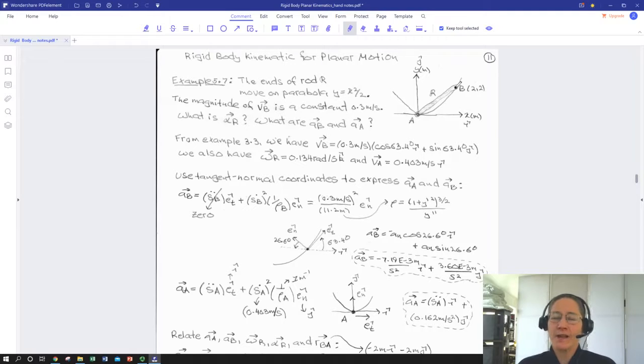And of course we can write an expression for a radius vector from B to A. Okay, so we've got all the components we need to deploy our acceleration of one point of a rigid body in terms of another, in terms of angular velocities and accelerations. And this time we've only got one rigid body and the reference frame that contains our path, so we don't have the complication of a second.